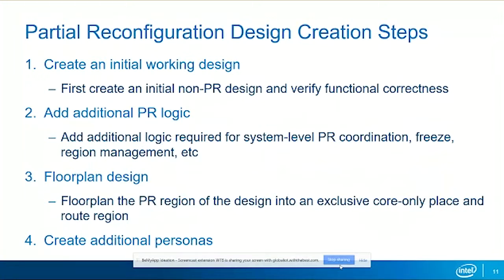So we'll talk about that, and that's really where the crux of what we're going to focus on with verification is. There is specific logic that you have to put into a PR design that you don't have to put in a typical FPGA design. And this is used to perform the PR operation and also to take care of your PR region effectively going through a change of functionality where it will go from working as function A to being taken offline to working as function B. And we'll talk about that in a bit more detail.